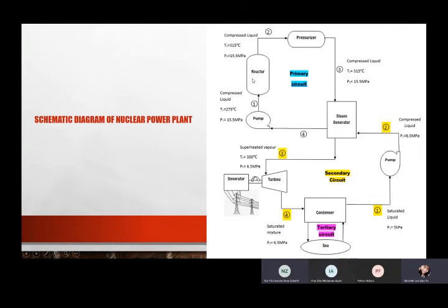uranium-235 is used in a pressurized water reactor (PWR) to undergo the nuclear fission chain reaction, which produces a large amount of heat. The heat is then transferred into the water inside the primary loop and flows into the heat exchanger, which is the steam generator. The heat is transferred through the walls of the tubes inside the steam generator to the lower pressure secondary loop of water. In the steam generator, the water of the secondary loop will boil and turn into steam.